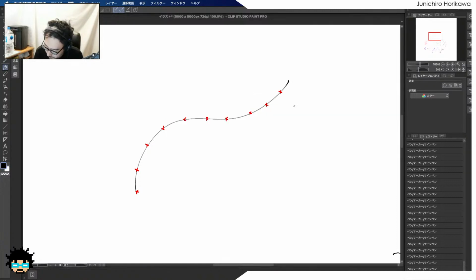And based on the current frame, I have picked up the U value, or point position value, which is in between this curve. Let's say this is the head position, and this is the tail position. As you can see, this point is not on top of the control points of this original geometry, but you do need to create additional points right here to trim out the curve, right?